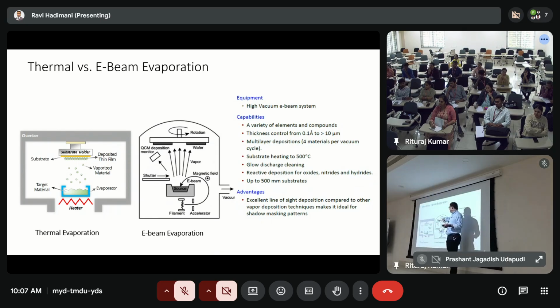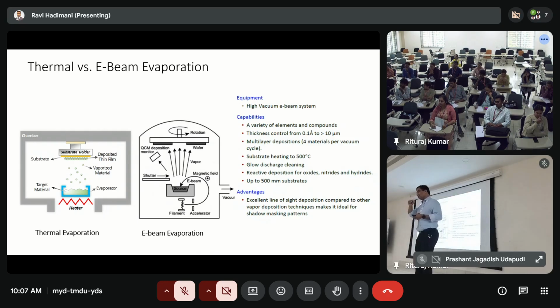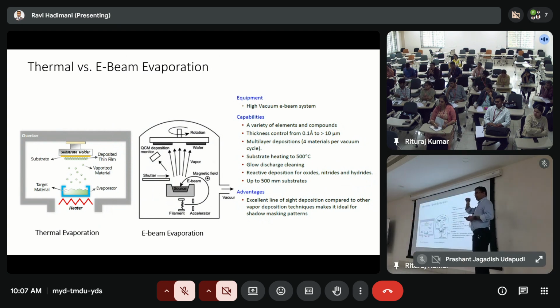It can tell you what the thickness is here. So you use quartz crystal microbalance, it's really nice. You can literally see how the thickness keeps increasing in nanometers as time passes, and the thickness is related to the frequency of the oscillation. I already gave the clue, but let's come back to that a little later. But so these are the two processes. I'll show how that works.